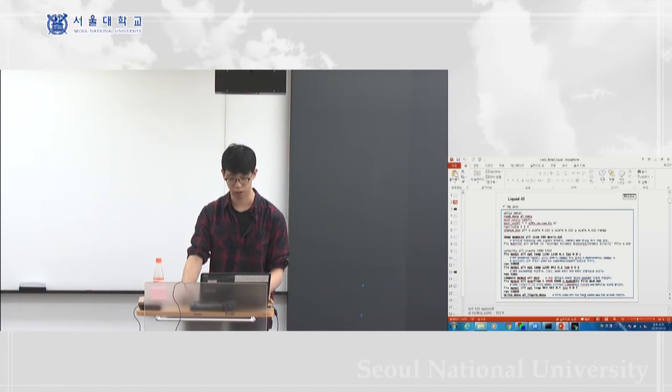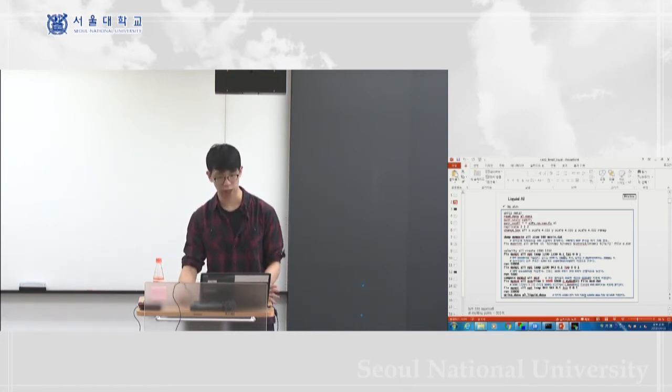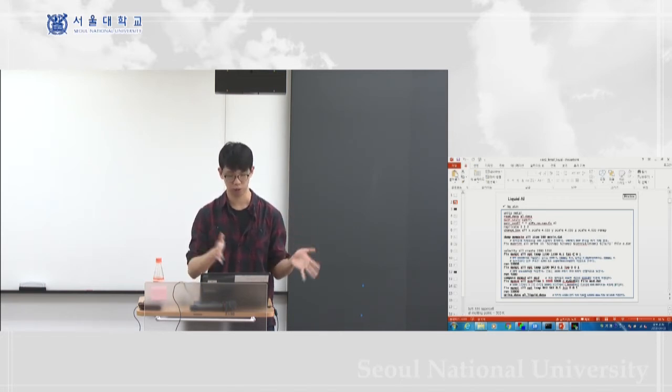And then the latter part is for the pressure part of the NPT command. So here we're going to apply the isotropic pressure over the simulation cell. The iso means that we're going to apply isotropic or hydrostatic pressure, and the next number is the starting pressure. So it is 0, so we're gonna add no external pressure on the simulation.